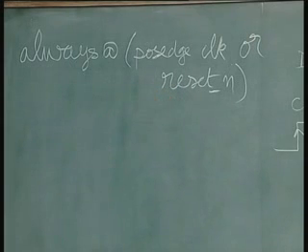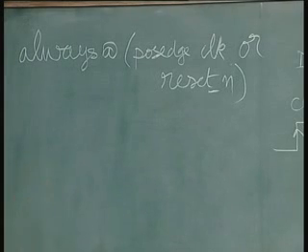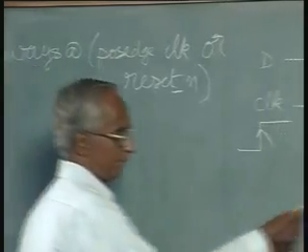And why should we go for reset underscore n, active low? In a big system, this reset will be residing as a master reset on a control panel, and you need to reset from there, and that will be connected via a long cable in general. Suppose the cable snaps, it should return to a safe value. So where the reset push button ends on the PCB, you just put a pull-up resistor.